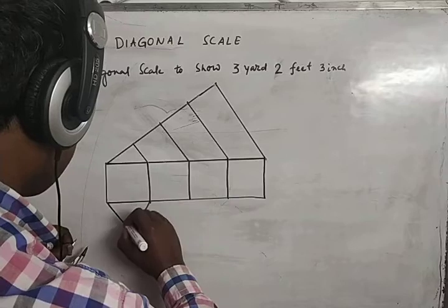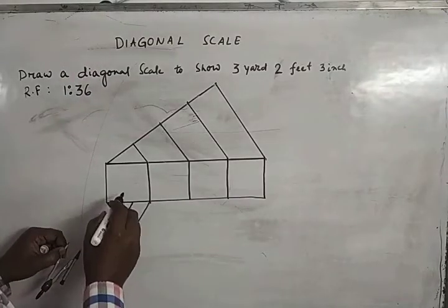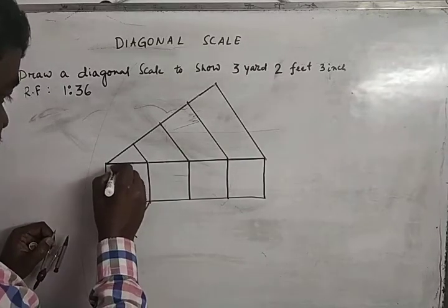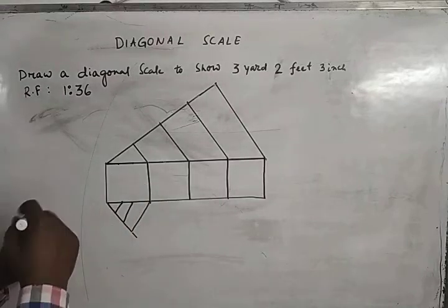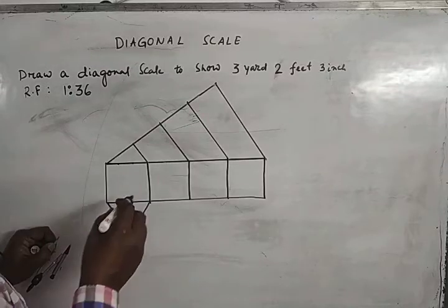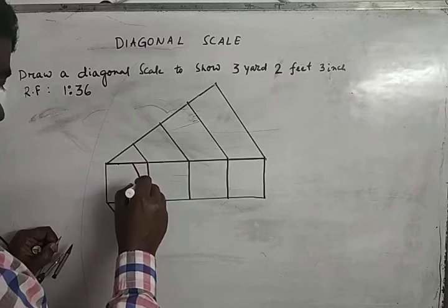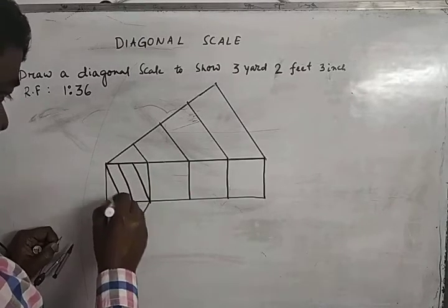By taking set square. Here take the points. Okay, but during addition, as it is a diagonal scale, that diagonal property is maintained in drawing the secondary division, so it has to be added diagonally.